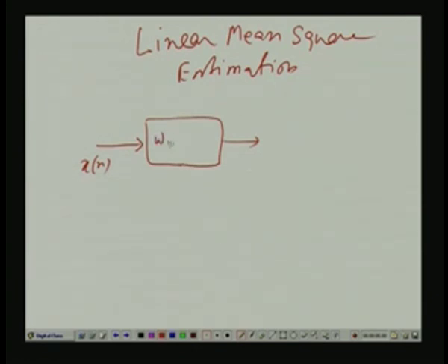you can denote the coefficients W0 to Wp, so that the output Yn becomes a very good estimate of some unknown signal Dn, called the desired response or target signal Dn. That means if you take the error, it is Dn minus Yn, and Yn depends not only on Xn but on the filter coefficients you choose. So, if you take the mod of En square, that is the variance of En, and all processes are assumed to be stationary here, then mod square of En will be a quadratic function of W0 to Wp.